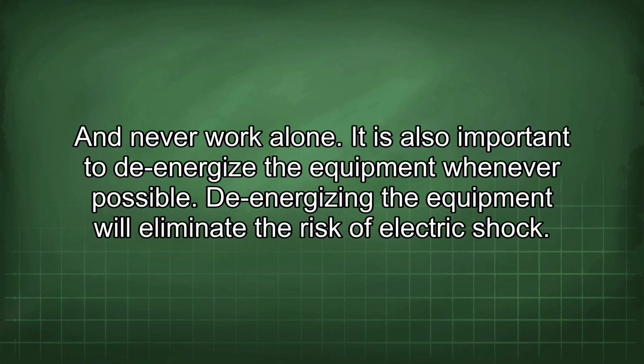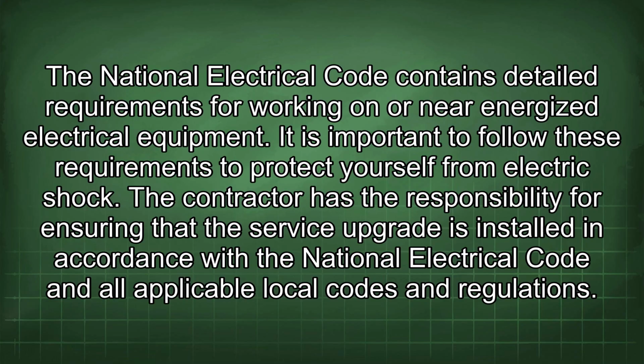It is also important to de-energize the equipment whenever possible. De-energizing the equipment will eliminate the risk of electric shock. The National Electrical Code contains detailed requirements for working on or near energized electrical equipment. It is important to follow these requirements to protect yourself from electric shock.